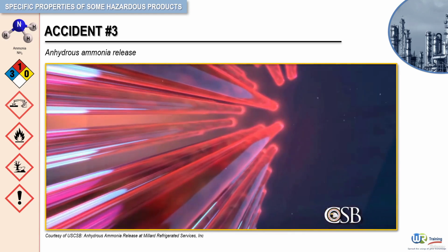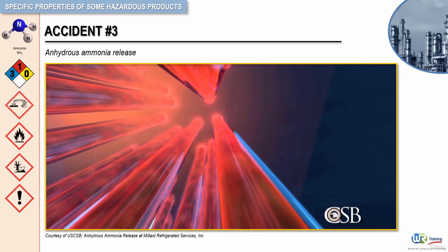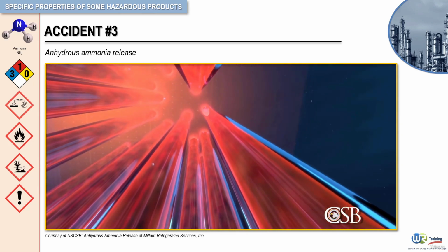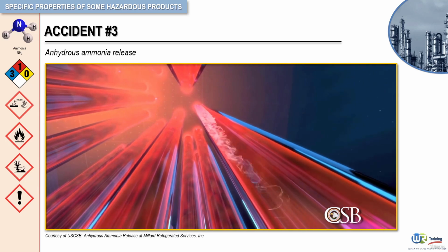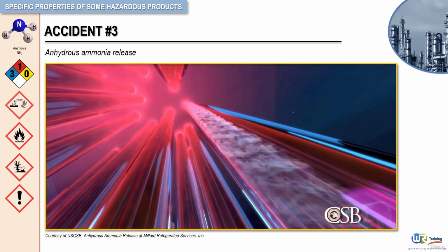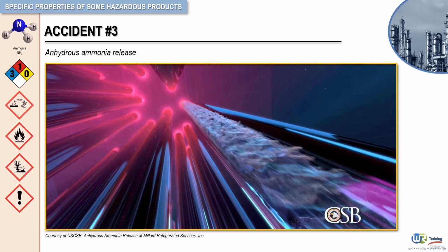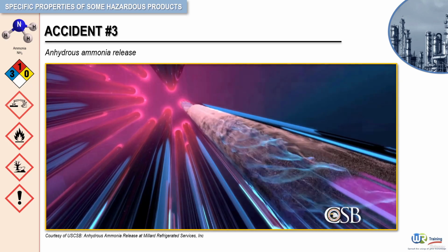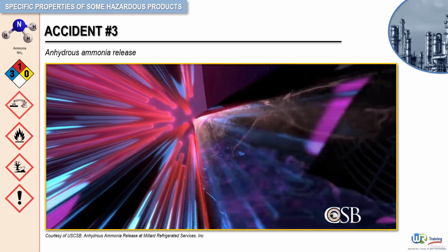The control system reset triggered a valve to open, and low-temperature liquid ammonia was fed back into the evaporator coils before removing the hot ammonia gas. This caused the hot, high-pressure ammonia gas to rapidly condense into a liquid. A vacuum was created, where the gas had condensed. The void sent a wave of liquid ammonia through the piping, causing a sudden pressure surge known as hydraulic shock.